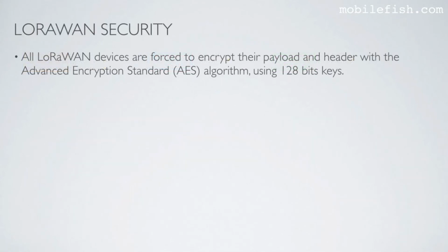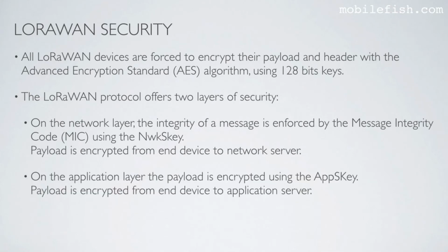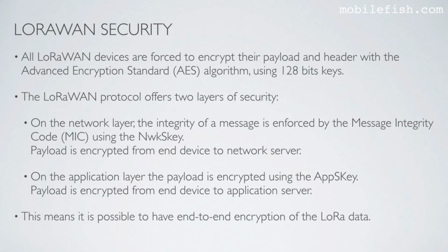All LoRaWAN devices are forced to encrypt their payload and header with the Advanced Encryption Standard algorithm using 128-bit keys. The LoRaWAN protocol offers two layers of security. On the network layer, the integrity of a message is enforced by the message integrity code using the network session key. The payload is encrypted from end device to network server. On the application layer, the payload is encrypted using the application session key. The payload is encrypted from end device to application server. This means it is possible to have end-to-end encryption of the LoRa data.